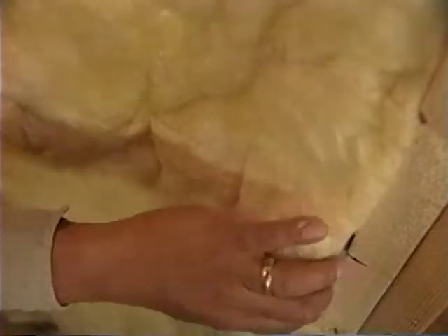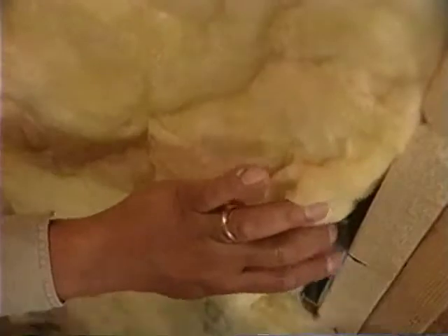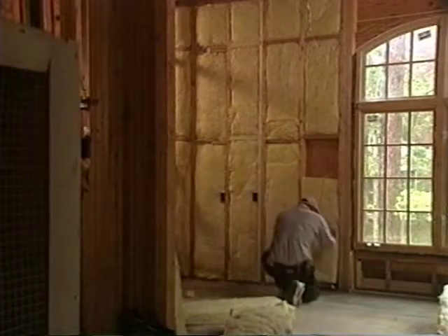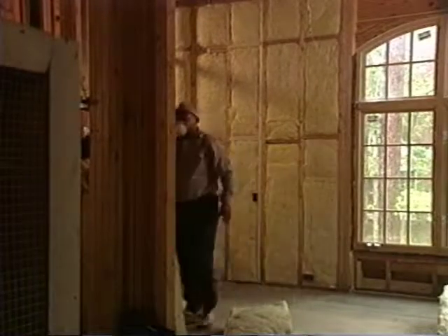When you have an electrical box in a stud cavity, it's also important to split the insulation. Take the back part and slip it behind the box. Then lay the top part of the bat on top of the box and cut around it. Careful not to leave any gaps. If you follow this procedure in walls, ceilings, and floors, you will reduce the amount of compression and allow the insulation to work at its full R value.